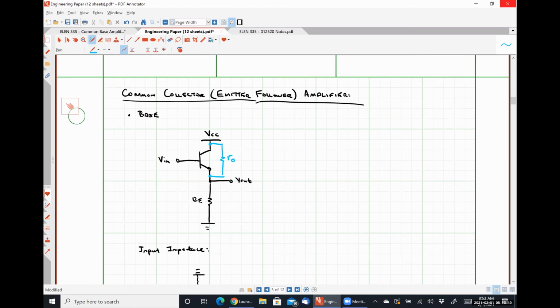A resistor R0 between the collector and the emitter, right? That's inherently what the early effect does, represents that change in collector current due to variations in VCE. We model that with a resistor placed between the collector and the emitter. Well, for all of our small signal analysis, where is that resistor R0 going to be placed?